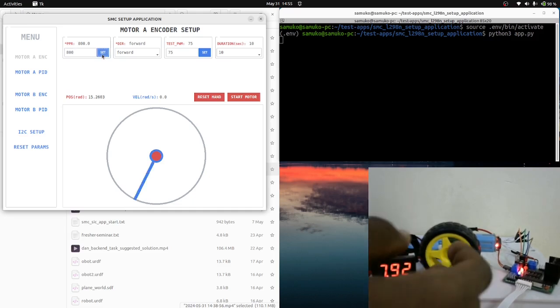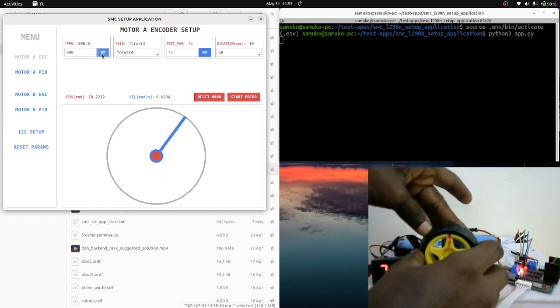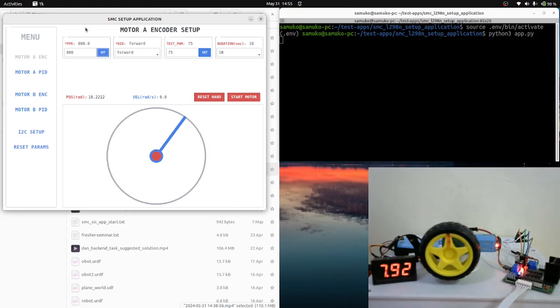The first step is to align the actual motor to the center. Then on the virtual, click on reset so that it will also be aligned. Then send the velocity. I want you to notice something. Notice that now the virtual motor is faster than the actual motor. Because of that, we have to increase it. So I'll go back to my previous initial value and increase it.